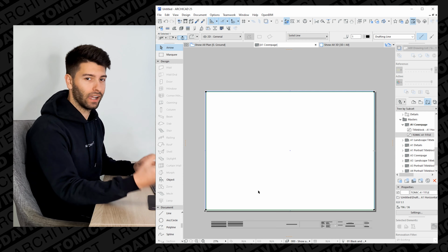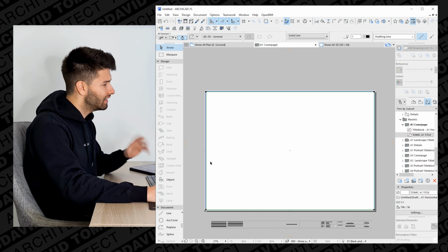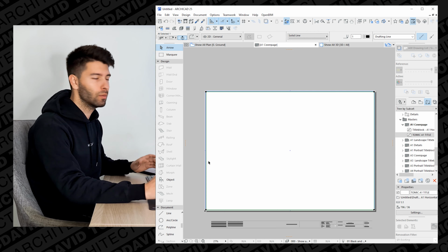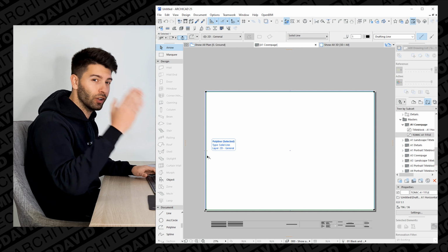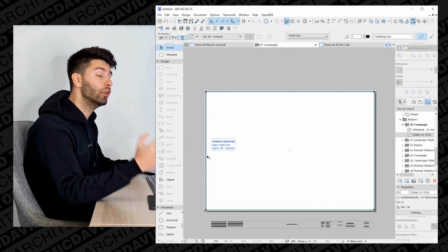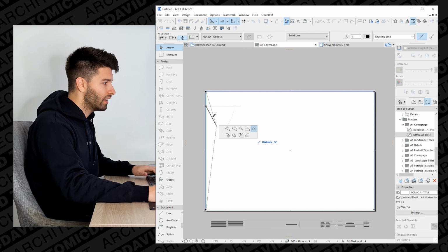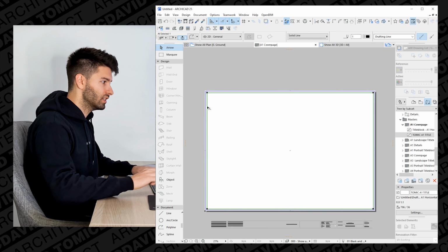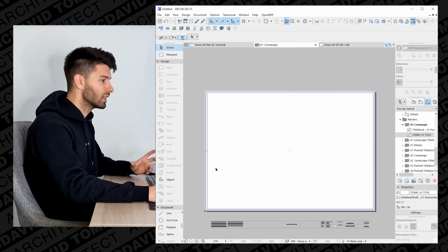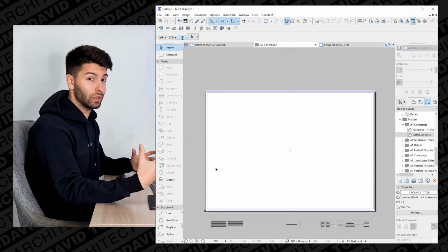So what we see now is an actual physical hard boundary printed on the box. This isn't necessarily required, but I really like to set a physical boundary on the drawing board. So if anything is printed and anything is lost on a different printer, you know where information has been lost. That's just a personal thing. What I then like to do is offset all the edges another 5mm to give us a very safe bleed area. This also gives us a really good place to put some copyright information, which we're going to get to right now.